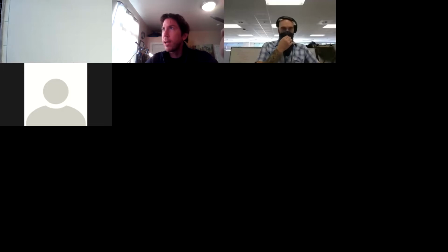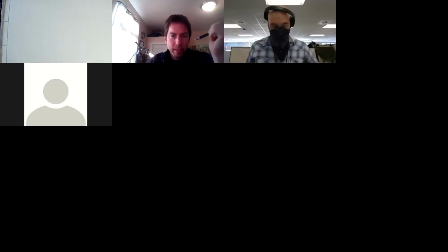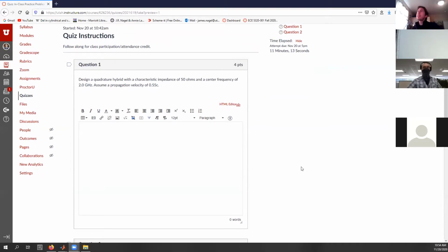So let's take a look at our practice work for today. Things are gonna get a little bit easier for the next few days, so we're just doing some basic practice problems. If you watched the lecture, you saw how we did the quadrature hybrid. I was racking my brain about the difference between a Wilkinson power divider and the quadrature hybrid, and really it's just that 90-degree phase shift at the output ports.